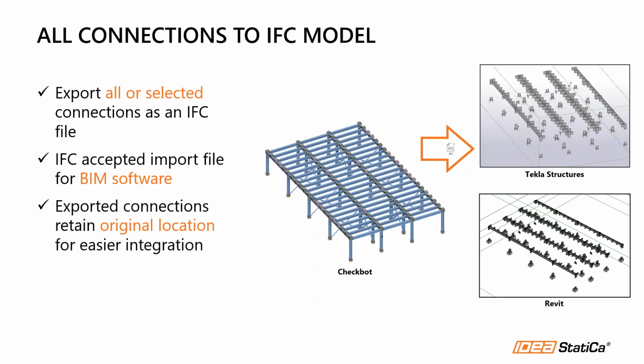All right, so we're just showing this example for this slide, but you can open it in your preferred application that opens IFC files. One important thing to mention is that the connections have their original coordinates, so this file can help you to detect any clash with other elements in your structure, right?